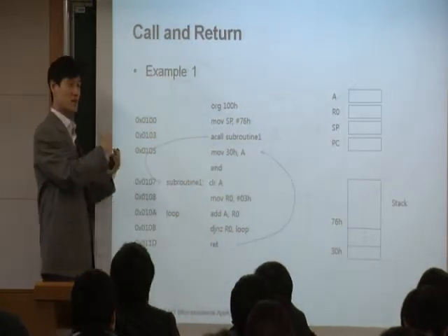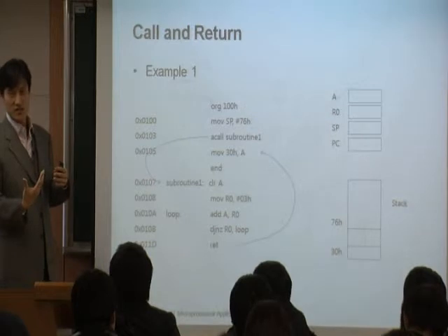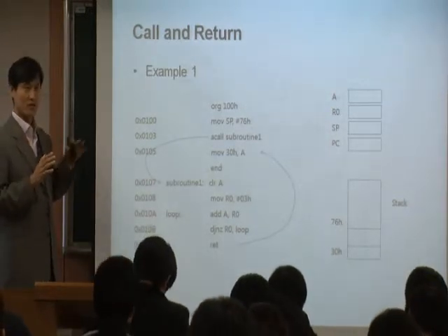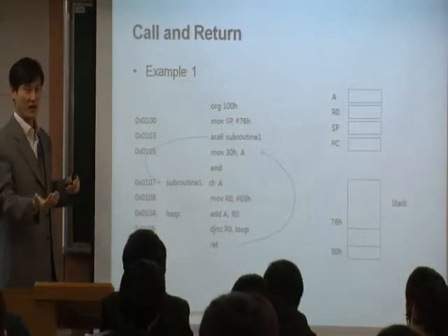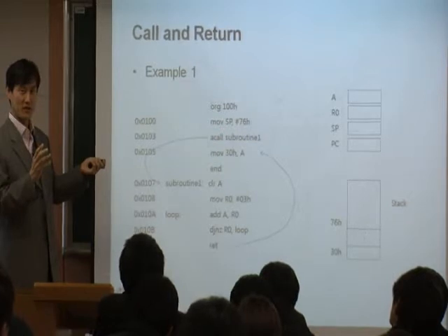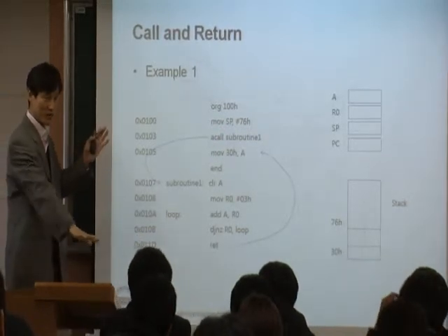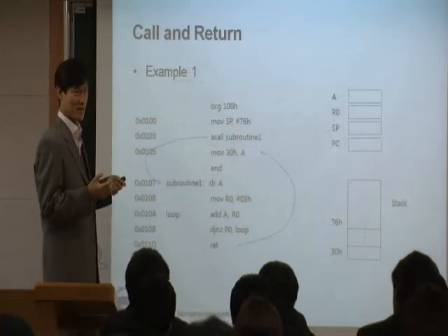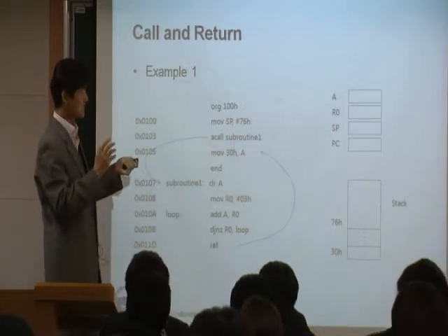In the previous jump and the simple instructions, we haven't used a stack before. This is the first time you start to use a stack. But when you use a stack, you have to define the stack pointer. Once you define the stack pointer, this is the bottom of my stack, then you can use a stack. So you have to define this stack pointer.